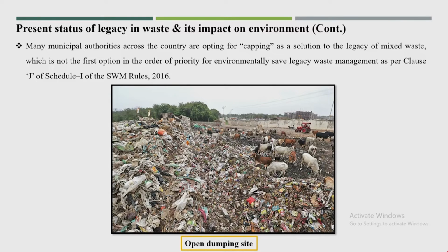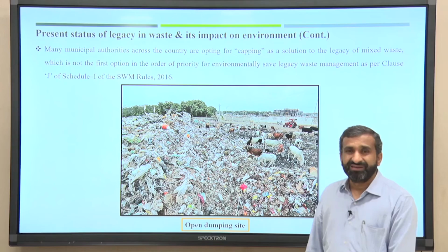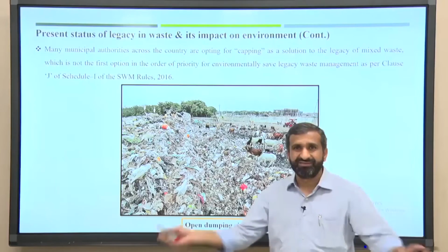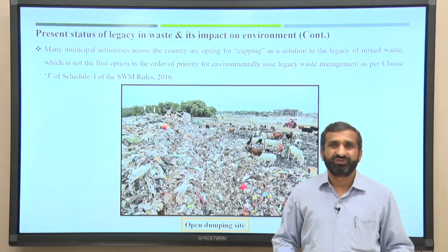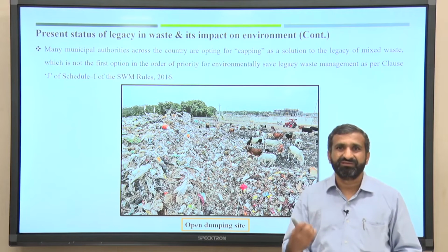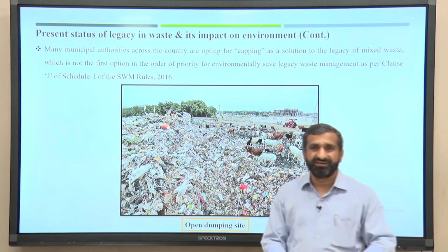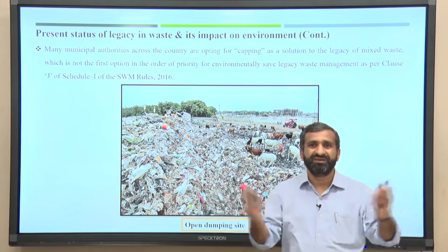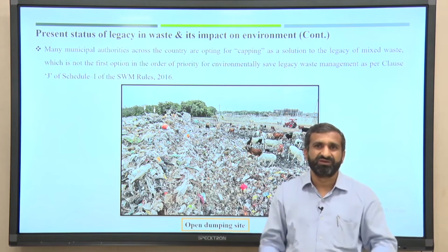Many municipal authorities across the country are opting for capping as a solution for legacy mixed waste. Some cities understood capping as closing the entire area and filling soil onto the top. If you are able to visit Surat, the dump sites, what they did was cap the entire area completely and fill soil onto the top of the waste material.